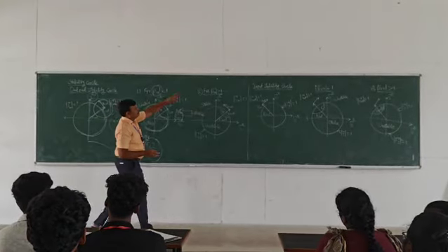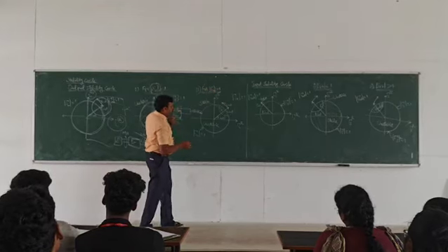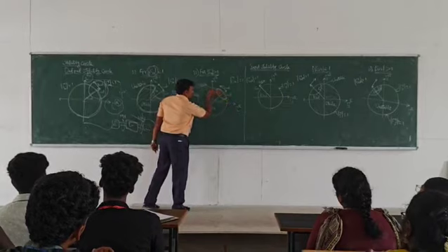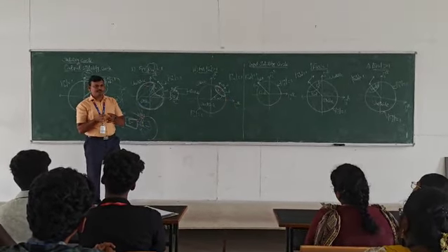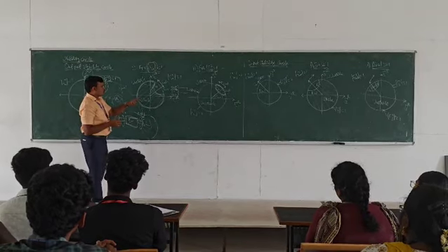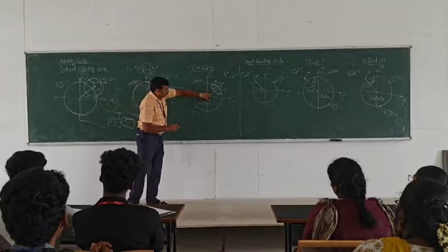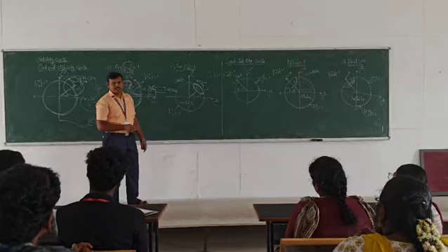When the modulus of S11 is greater than 1, only this smaller portion represents stability. These are the two main differences at the output side. In the output stability circle, the major circle is unstable and the smaller circle is the stable one.